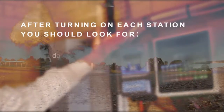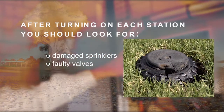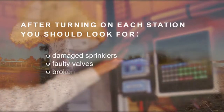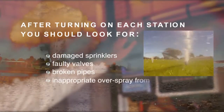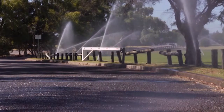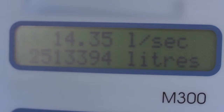After turning on each station, you should look for damaged sprinklers, faulty valves, broken pipes, and if there is any inappropriate overspray from sprinklers while operating, for example, throwing water over a roadway. This is a good opportunity to record the pump operating pressure for each station and to check that the water meter is operating.